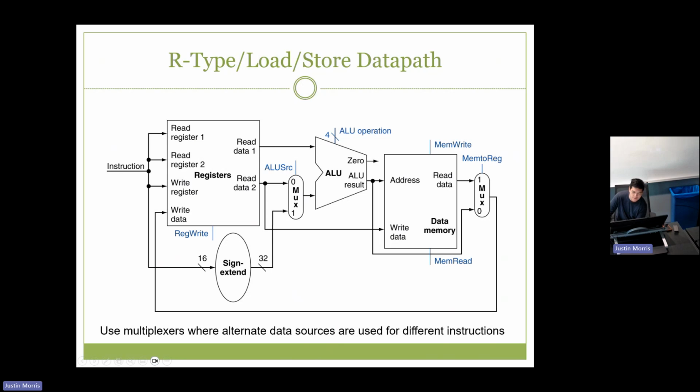So we're again sharing this write data port as well as the write register, right? The mux to share the write data port is shown here, and it has the control signal MemToReg. If we are an R type, MemToReg needs to be 0. If we are a load word, MemToReg needs to be a 1. And that's how we're sharing the write data.